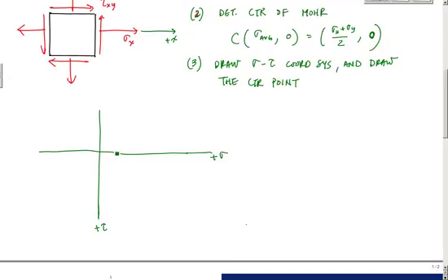Okay, and the reason is because when you rotate a Mohr circle, and we'll get to this in a little bit, when you rotate a Mohr circle clockwise, we want that transformation to be 1 to 1, if you will. What I want is that if I rotate clockwise in Mohr's circle, I rotate clockwise in my stress state.